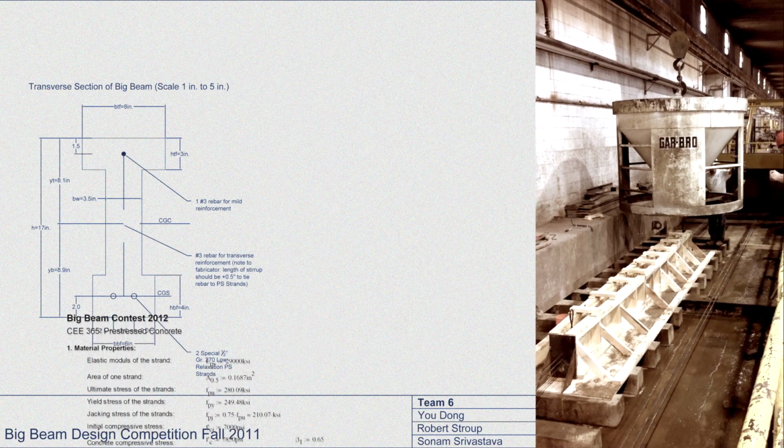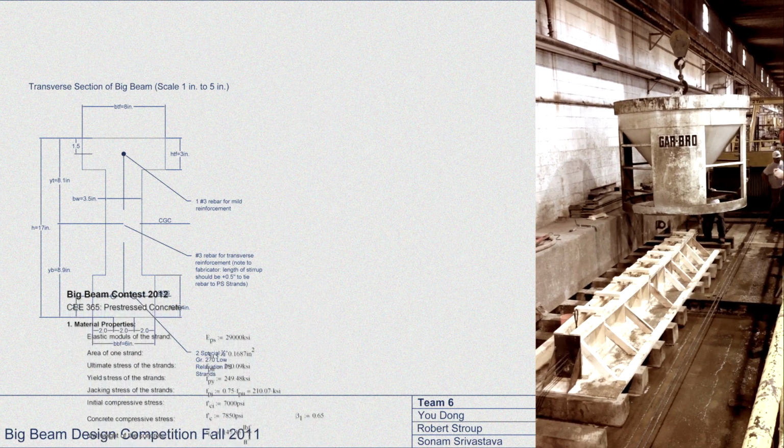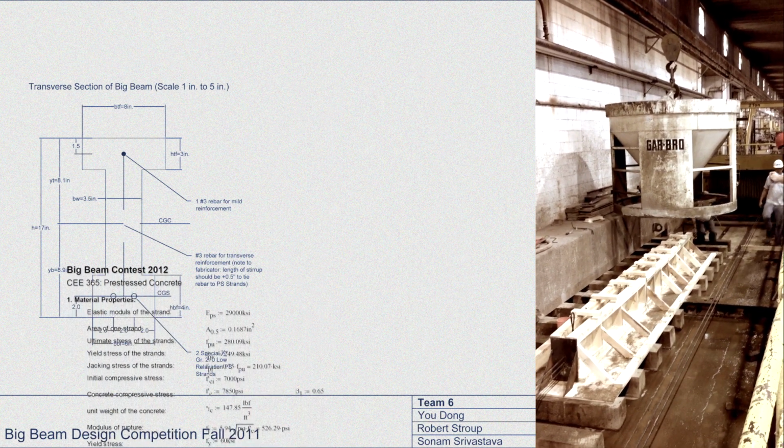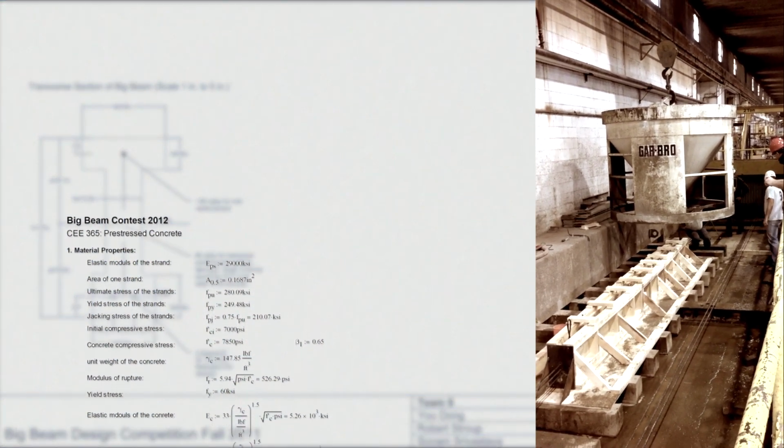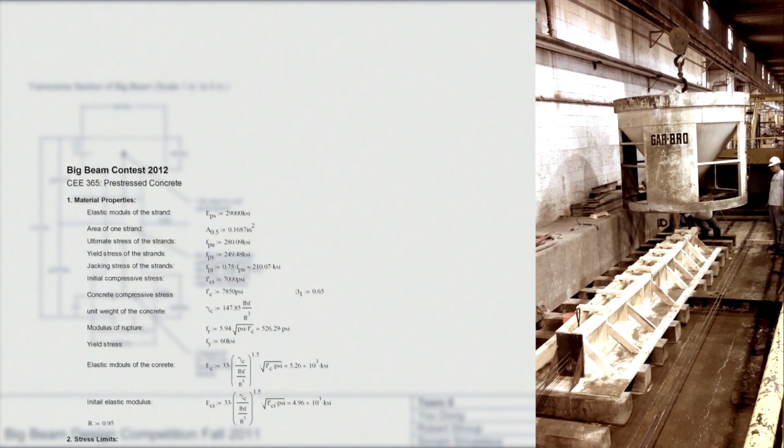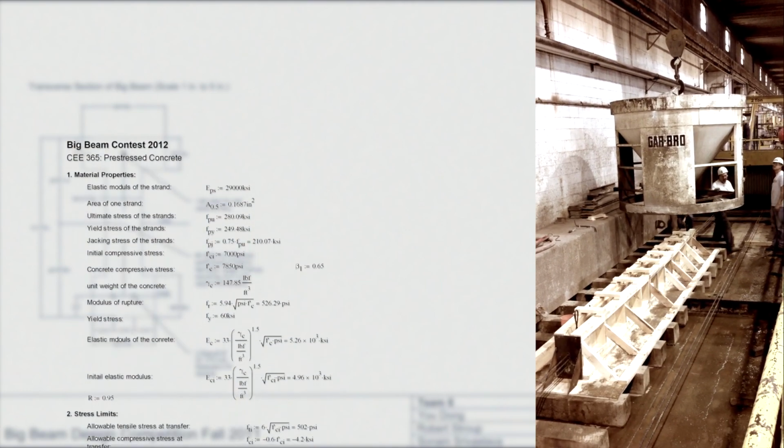The project involved an 18-foot-long beam with a span of 16 feet, subjected to two unfactored 10-kip point loads and two additional factored 16-kip point loads, both of which were applied 6 feet inwards from both supports.